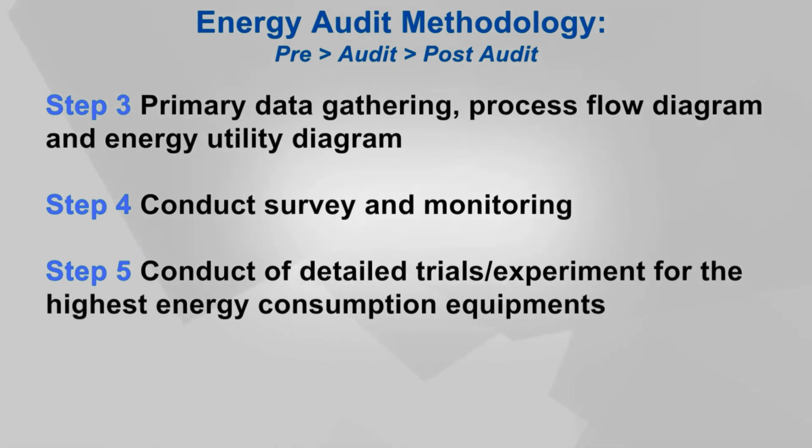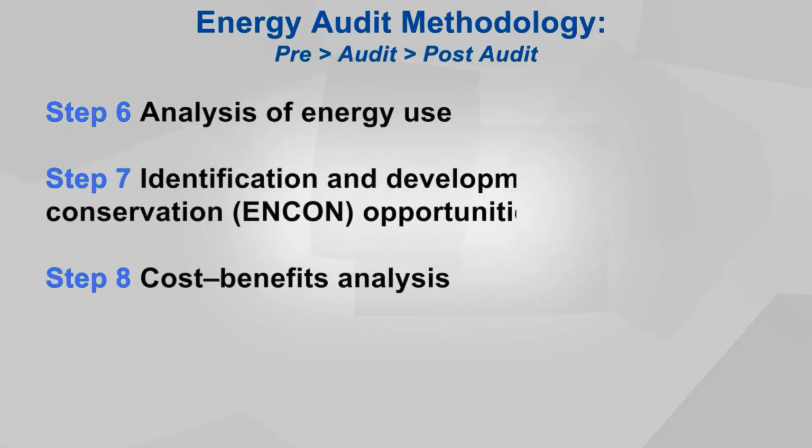Next one is identifying the energy systems and equipment. The energy audit team identifies the major energy consuming systems and equipment within the facility. This may include HVAC systems, lighting, production machinery, compressed air systems, and other significant energy users. Understanding the layout and operation of these systems is essential for planning the audit activities.